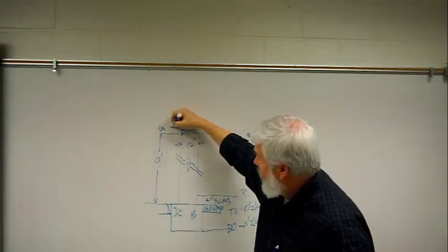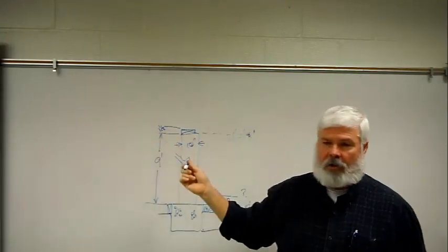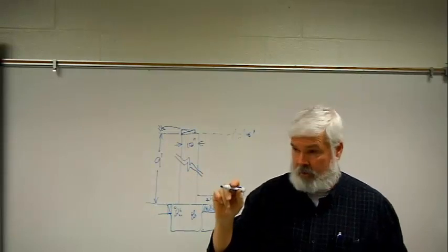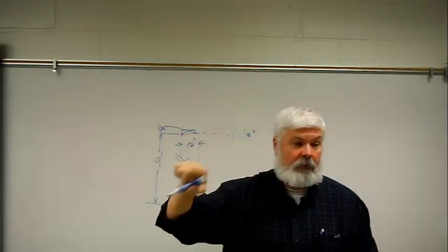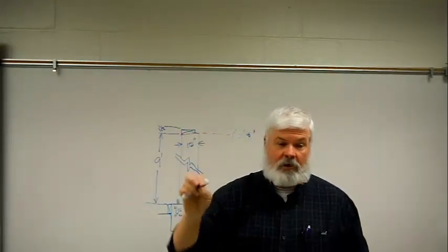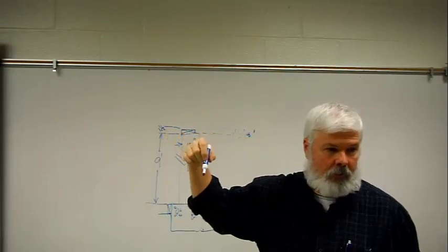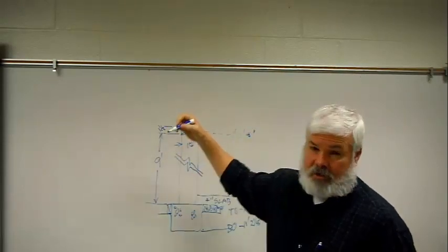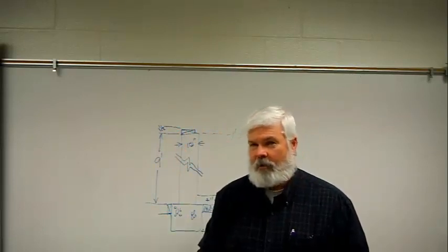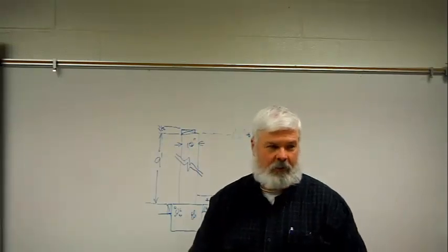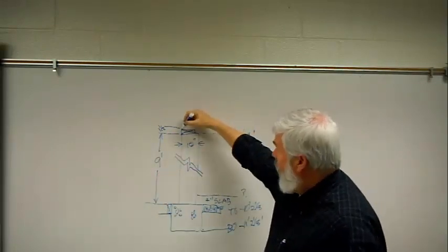Now, just a side note here, what is special about that material that sits out here on a concrete wall that can get moist, Jack? Yes, it's a pressure-treated piece of lumber which resists rot from moisture, and it also resists insects. There's one little type of insect that doesn't like to eat the chemicals that are infused into the lumber. The chemicals that used to be infused were arsenic, but the EPA got smart, and because that arsenic was leaching into the ground, there were dangerous chemicals in areas that had pressure-treated lumber on the ground. So that was outlawed.